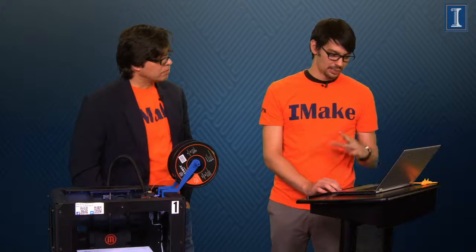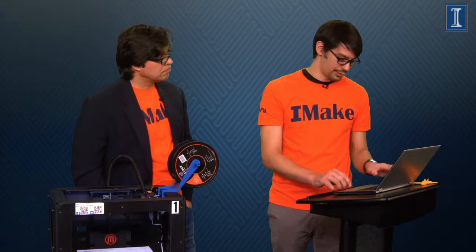That's right. So we can change this setting to speed up or slow down the print depending on what your need is. And as I mentioned, since it's only aesthetic, we can drop this down to 5% and print it that way. It sounds like the infill consideration is influenced by two factors. One, the amount of time that you have. If you're pressed for time, perhaps you make an object a bit more hollow. And second is what you plan to do with the object. If it's just sitting on your desktop and people are looking at it, then it can basically be a hollow object. Versus if it's a bracket that's holding something heavy, you may want something that's a bit more solid inside.